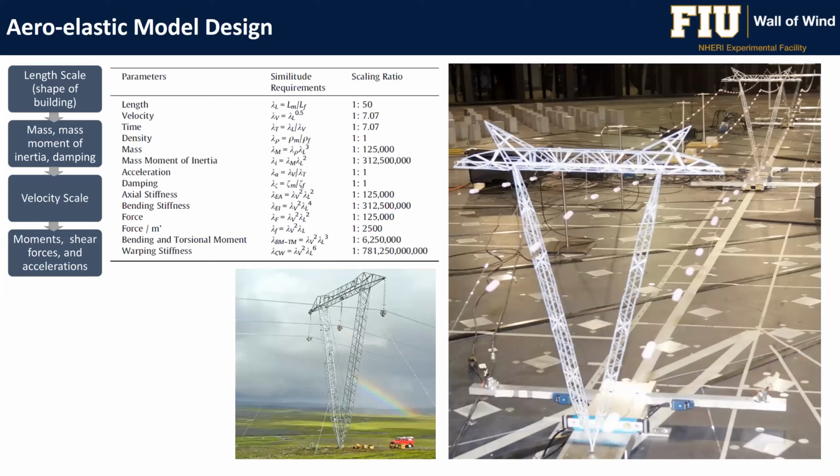The previous video actually showed that we were able to control the sectional model by side actuation system, but we also can do a full modeling of the entire dynamic properties of the structure in terms of stiffness, mass, moment of inertia, and other scaling items. So we have to follow a long list of scaling ratios so that we can replicate the dynamic properties, mode shapes, and modal frequencies of the structure of interest. Next.